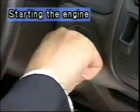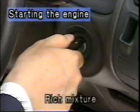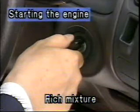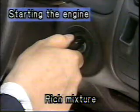Now let's consider different driving conditions, beginning from when the vehicle is started. Naturally, the engine is cold, making it harder for the fuel to be atomized. This alone is enough to create an improper air-fuel mixture. Hence, it is necessary to provide a greater ratio of fuel to air.